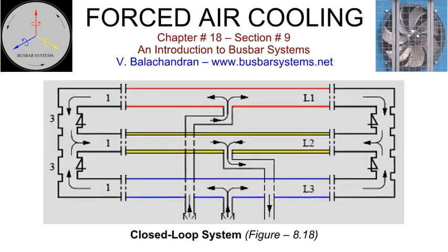Closed loop system. In a closed loop system, different airflow pattern and direction of flow can be established. This will depend upon the layout of the isolated phase bus bar. Air can be fed into extreme 2 phases, through a common manifold, near the generator. Air travels to the end near the generator transformer where it is led into the center phase through suitable aluminium ducts. The return air travels through the middle phase and is evacuated through an outlet that is located very close to the inlet manifold. The inlet and the outlet are connected to the forced air cooling equipment.